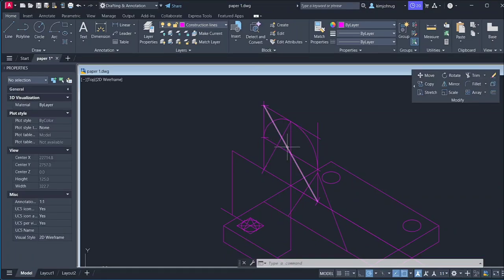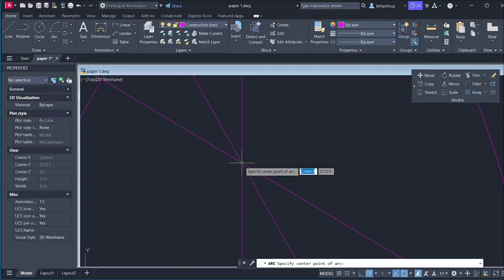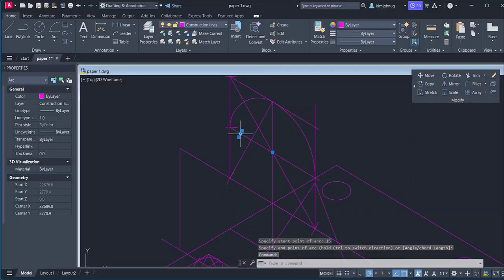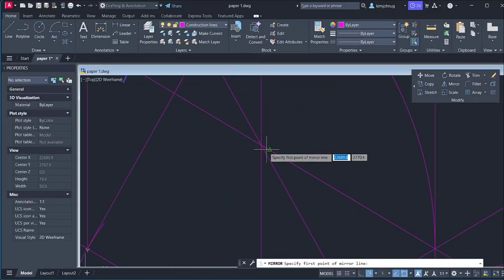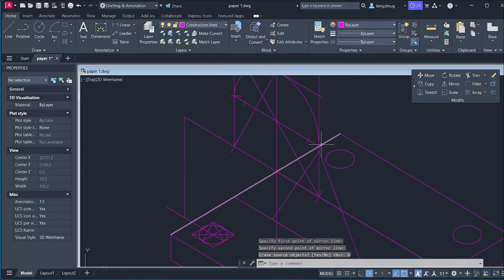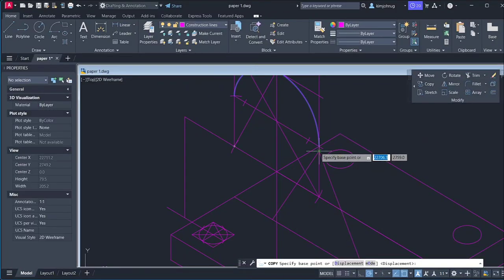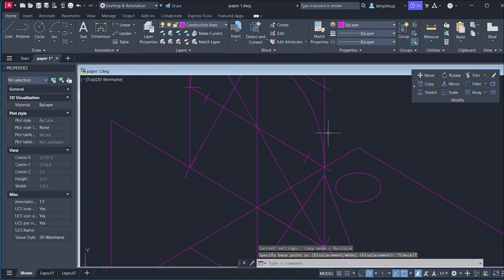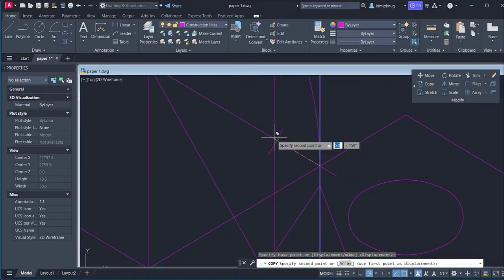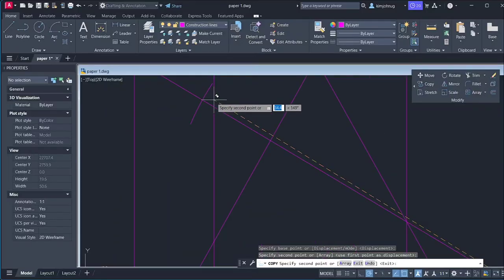So in here, there's a circle of diameter 30. I'm going to use the center lines. They're going to just guide me. So diameter 30, meaning the radius is 15. Just measure 15. Mirror. An angle of 60, right? Yeah, it's there. I want to copy this line as it is. I selected the square. Copy this line, move it from here, and then also copy this side.